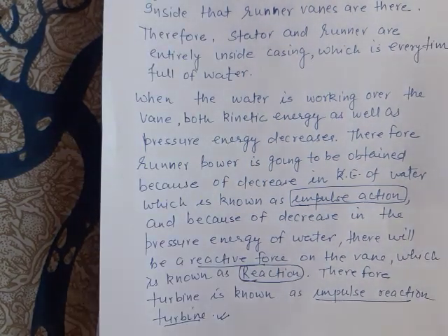I think it is very much clear to you. Let me again repeat the concept of reaction turbine. In impulse reaction turbine, the runner power is obtained as a result of decrease in the kinetic energy of water when the water is working on the vane, and also the pressure energy of the water decreases when the water is working over the vane.